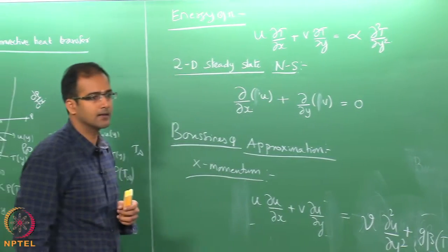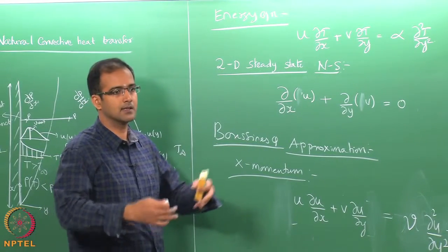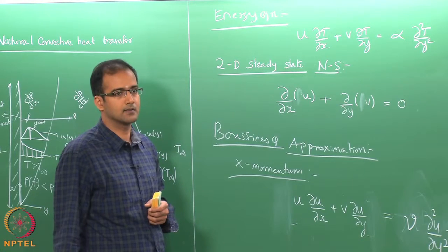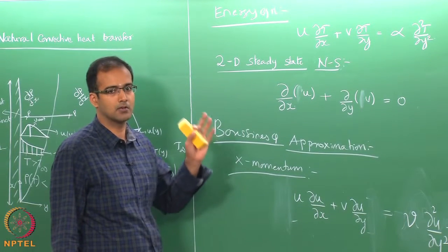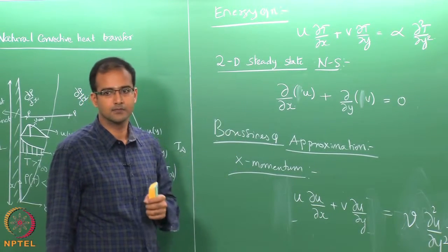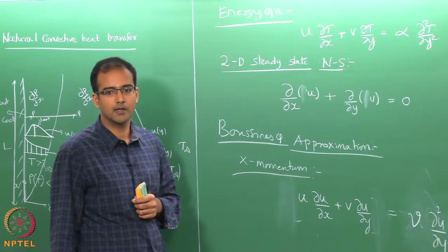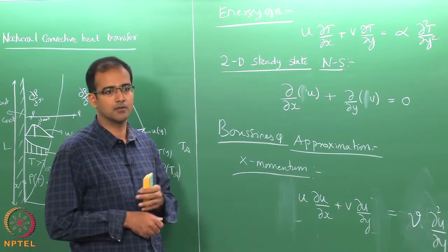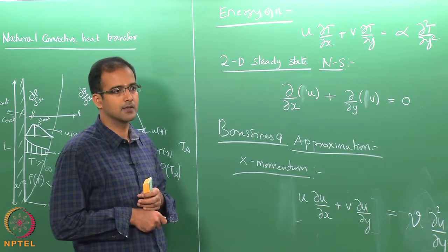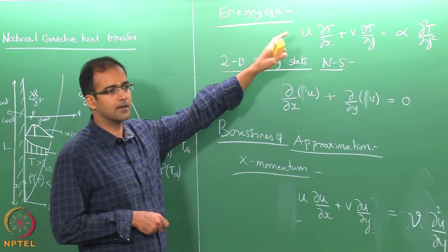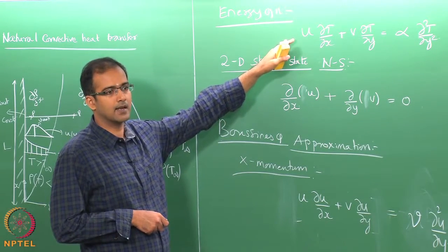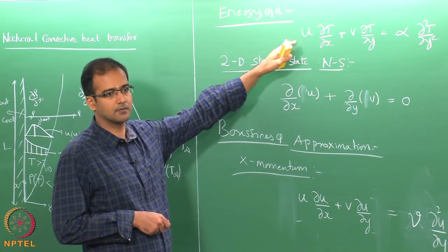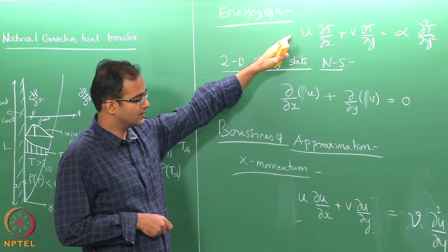You can neglect again heat diffusion in the x direction with respect to y, and if you also neglect the viscous dissipation, we are talking about small values of Eckert numbers. In that case this will be the same as your external laminar forced convection past a flat plate. So, this will not change.